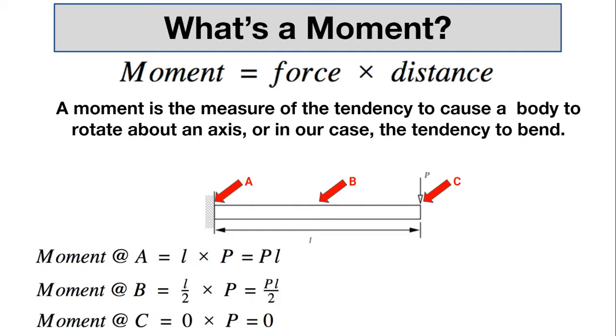The key to remember, once again, is that stress is the distribution of internal forces in a member. Strain is change in length over length, so it gives you an idea of how much deformation is going on in the member due to that stress. In a cantilever, there's bending stress, which means across that cross-section, the stress is not the same as it goes from tension on the top, positive on the top, to compression on the bottom, negative on the bottom. Somewhere in the middle at the neutral axis, it's going to be 0. The farther away you are from the load, the higher the stress is, because the higher the moment is. We'll pick up on this in the next video.